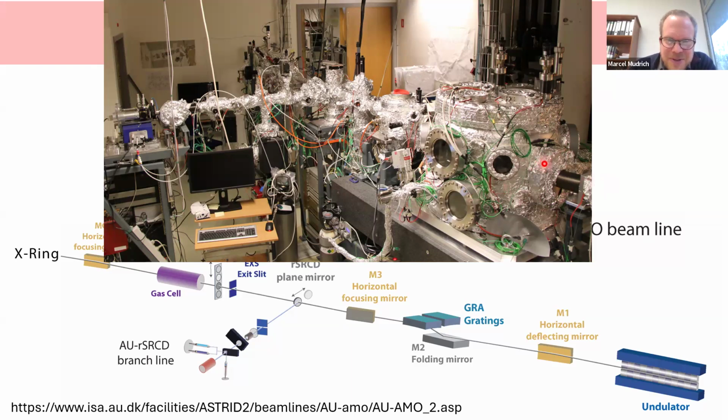This is, of course, with no X-rays going through. This is just for preparation. By heating up the surfaces, we outgas and evaporate any dirt and any contamination that is present inside the vacuum vessels. So that is evaporated off the surface and pumped away by efficient pumps.